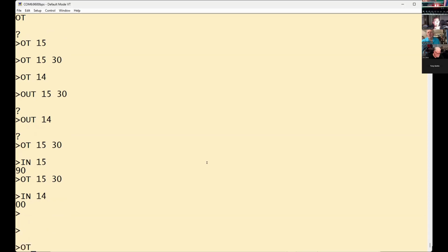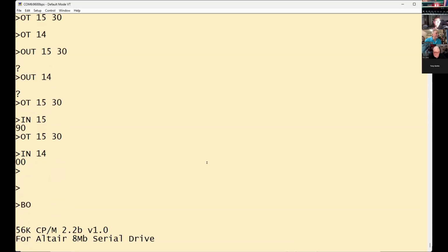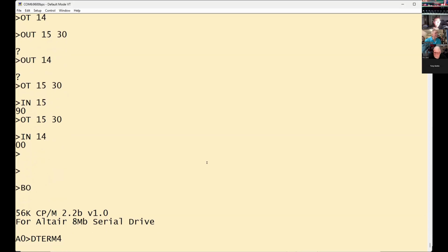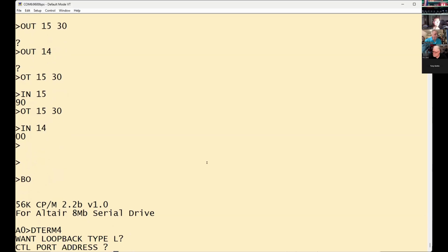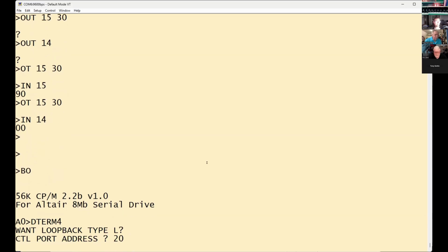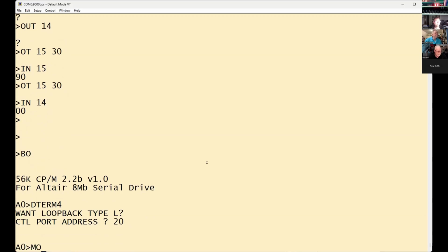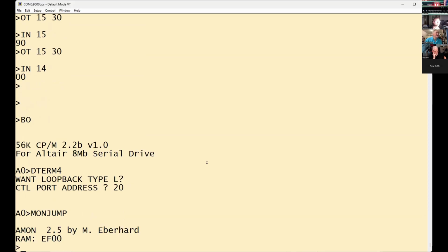Hey Walt, you may need to reset the chip again because you did an out 14 without an argument, and I don't know if it sends a 0 or does nothing. So if it sent a 0, we'll probably need to reinitialize it again. Well, that looks promising. So we'll have to do an out 14 3. OT.